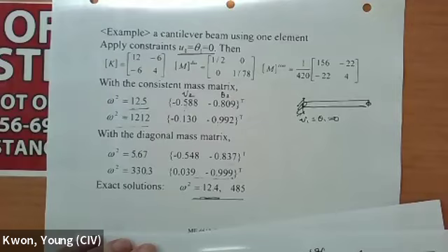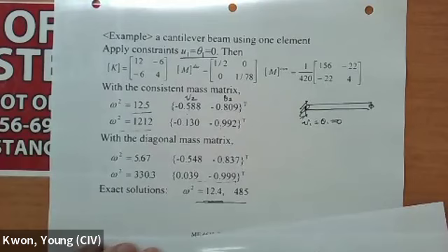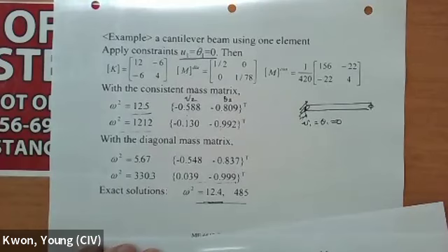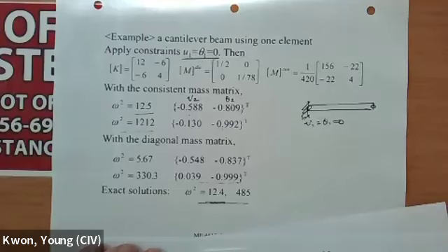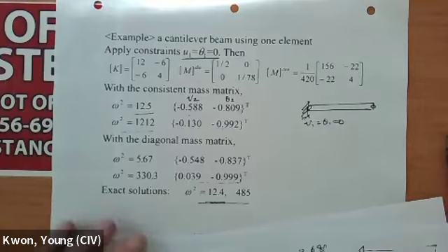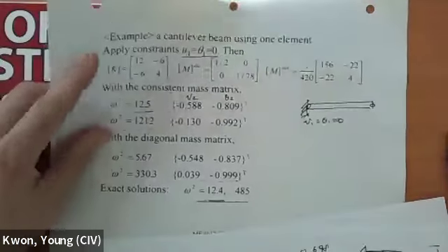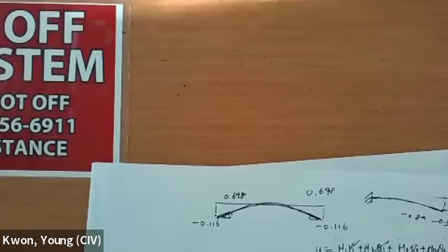If you want up to 10 and you have only 20 degrees of freedom in the representation, then your higher mode shapes are not going to be that accurate. So you have to have at least 100 or something like that. Then your frequencies and mode shapes are going to be accurate up to the first 10 modes. Do you get it? Okay.